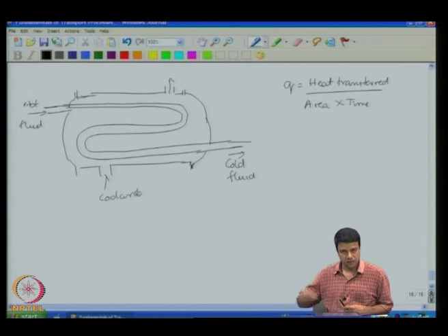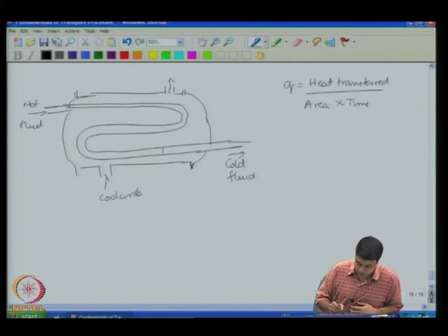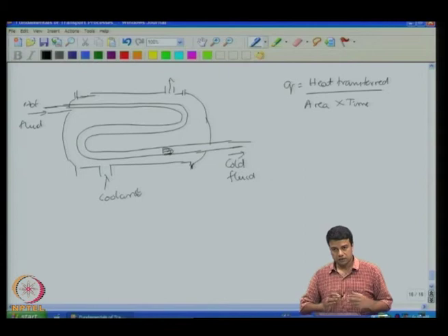Also, the heat is being swept through the heat exchanger due to convection. So, it is also going to depend upon the velocity with which the heat is going through. In addition, it is not going to depend only upon the mean velocity, it is also going to depend upon the details of how the flow is within the tube of the heat exchanger. If the flow is of a laminar type, you have nice straight streamlines, you will have a lower heat transfer rate. If it is a highly mixed turbulent velocity profile, then the mixing is far more efficient and you will have a different heat transfer rate. So, it is also going to depend upon the fluid flow properties, that is the density, the viscosity and the velocity. So, let us assemble all of these.